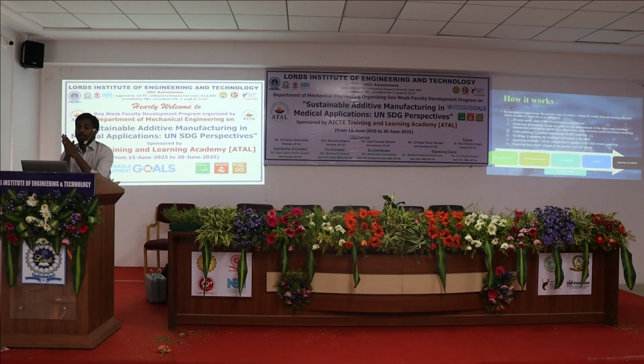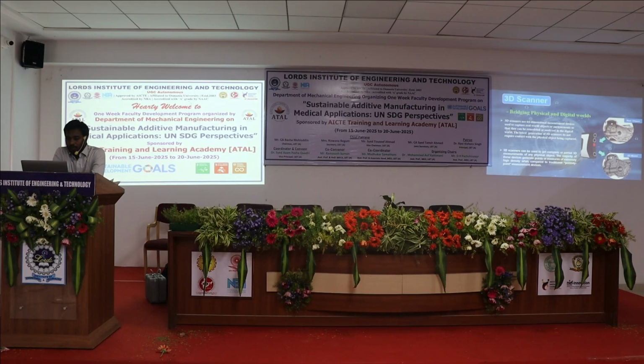So it works like this: after scanning, we get a virtual model in software, and then we compare it with the physical model. It comes as scan mesh data, and then we extract the information with software like Geomagic from the mesh data and convert it into a 3D model. This is a white light scanner.